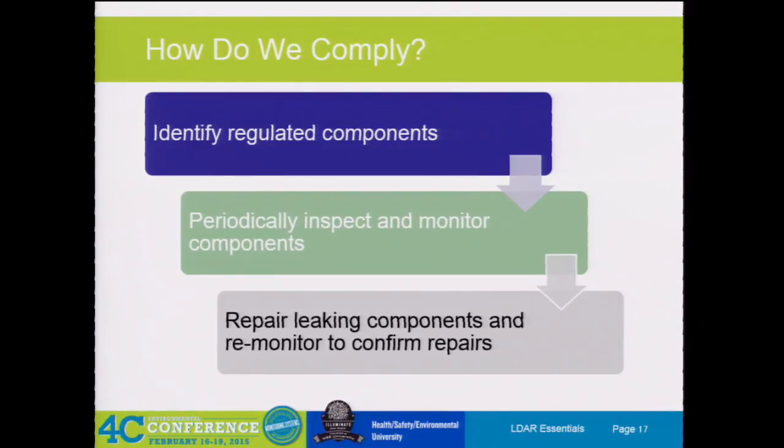Delay of repair. Are you familiar with the regs heavily? In a delay of repair, you have to have a tag on it at all times till it comes off. So I would make sure when you're looking that you have a weatherproof tag, which is basically any LDAR tag that y'all have right now for your leak tags. You want to make sure you have it on there, so if somebody does come in, or yourself, you can pull your DOR list and actually walk out there and see if you have a tag.